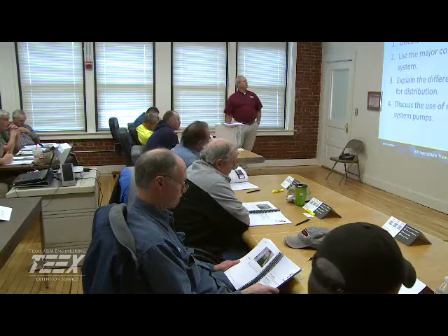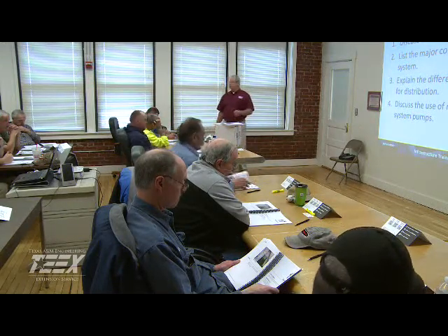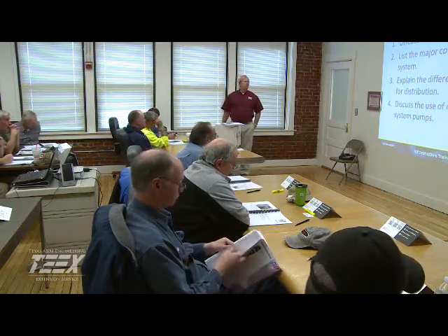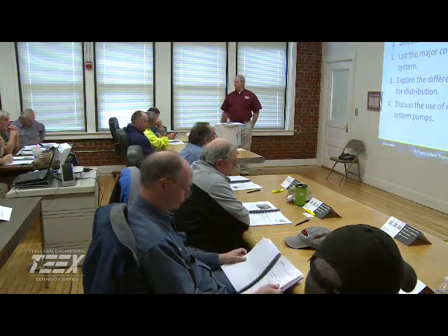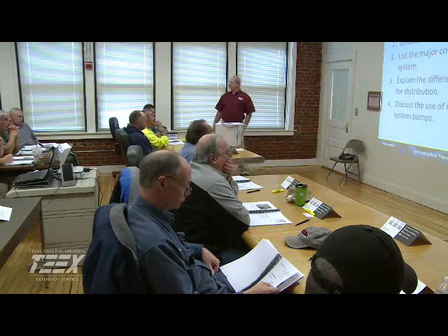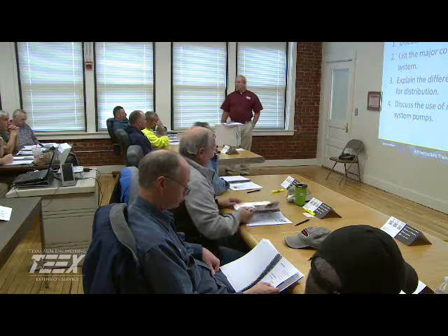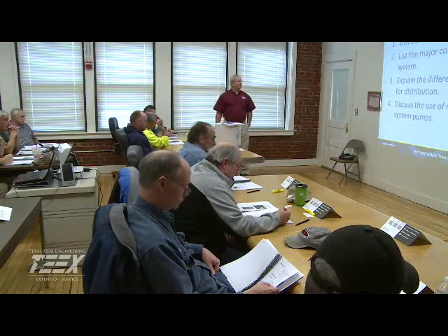So first of all, we're going to discuss the different types of storage. And you know, we have ground storage, clear well, standpipes, and elevated storage. List the major components of the distribution system. You know, some people have transmission lines, outfalls, we have mains, sub-mains, and then sometimes we have laterals, and then we have our service lines going to our customers.